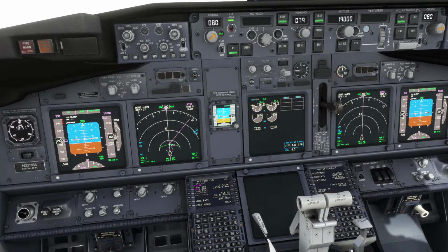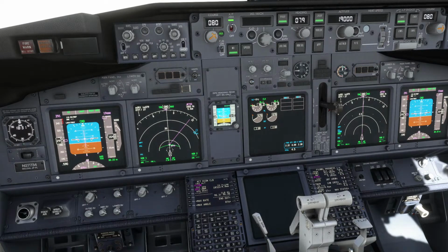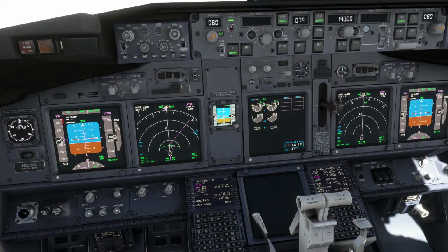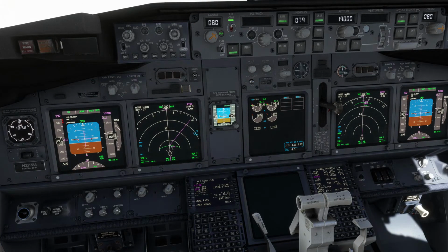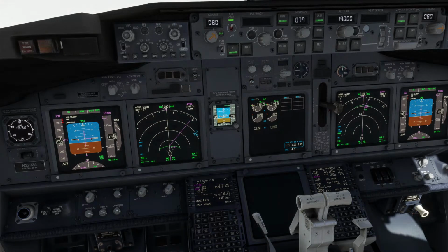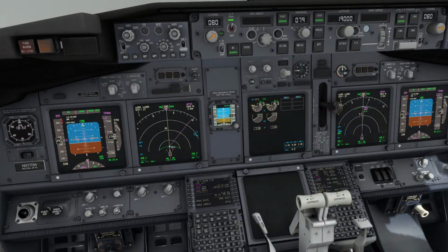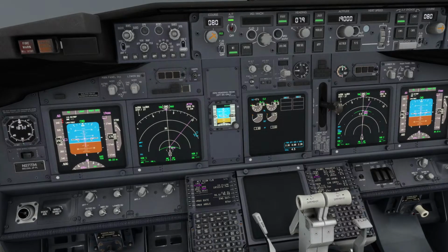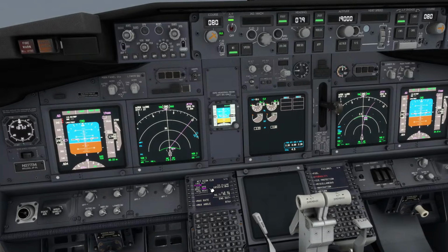It's not wrong, it's just that the FSi panel is asking what is wrong. You are clearing to flight levels below transition altitude, because as you mentioned on the lesson plan, transition altitude here is 18,000 feet. So instead of flight level 150, it should be 15,000 feet. Instead of flight level 90, it should be 9,000 feet. That's the only thing. Not a big deal. But as you mentioned on the lesson plan, the transition altitude is 18,000 feet, and it's correctly selected on the FMC. It's a good idea to change it.